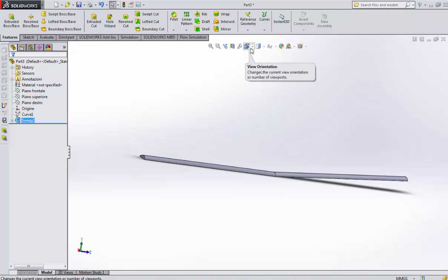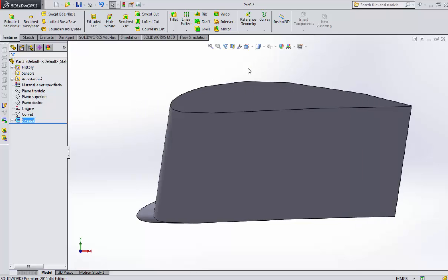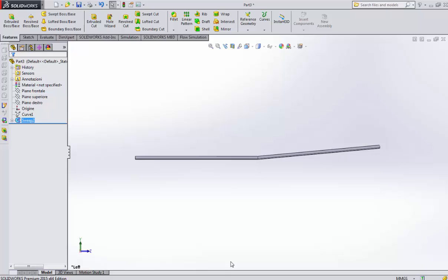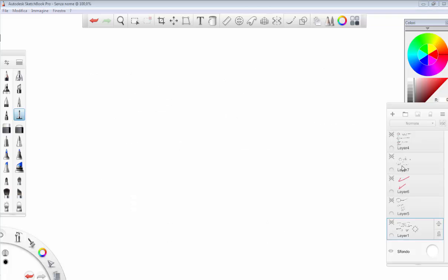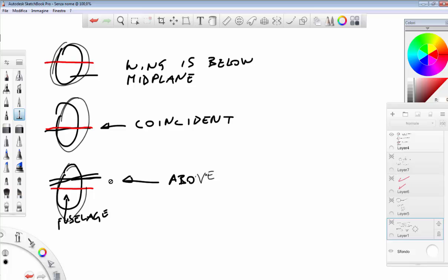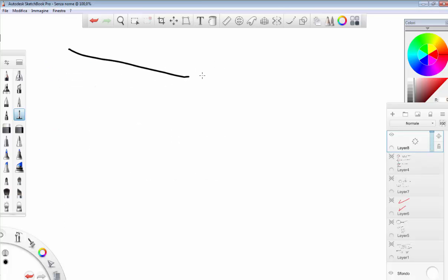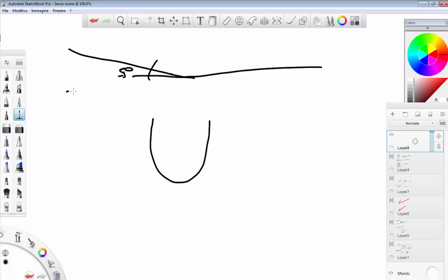This is your choice, but this kind of wing that we have drawn can be used in case you are thinking of high wing dihedral, because we have this dihedral, I mean this is 5 degrees, so you can use it on your wing, on your airplane.